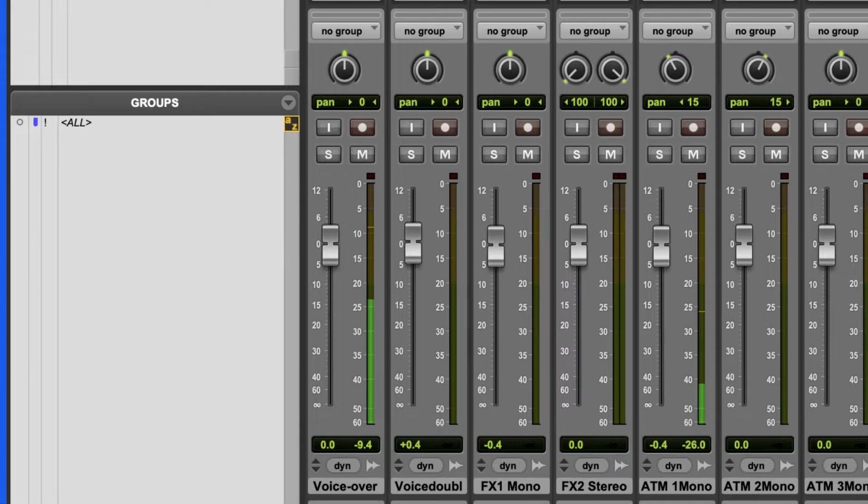When recording, you must ensure that the peak level does not hit 0 dB, as this will result in unpleasant distortion. The red light at the top of the meter will hold when you hit or exceed 0 dB. You'll soon learn that it is difficult to predict how high the peaks of any sound will go. Therefore, you should leave a margin of error known as headroom.